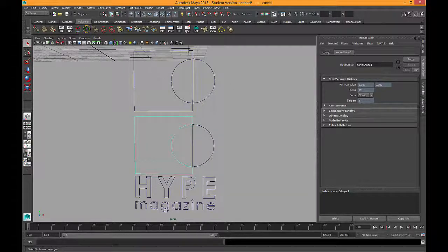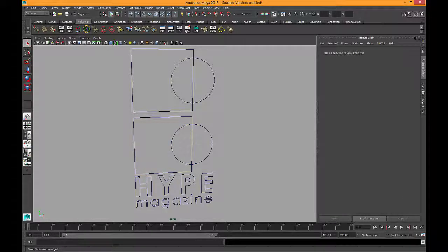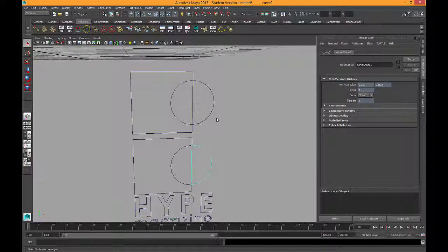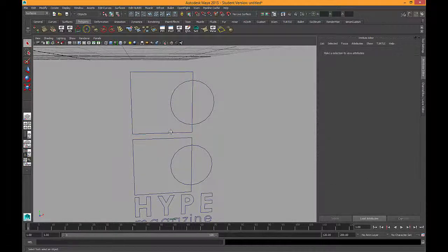And you can see the difference between these two. I wanted to show you this difference. This bottom one is the object I set up using the Pathfinder tool. So I cut this piece out between the square and the circle. What that's resulted in is one curve in this shape and a separate curve in this shape. Where I just overlaid the two shapes, what I've got is a full circle and a full square. Even though both of these two objects look exactly the same, they're actually different, and it'll give you a different result.